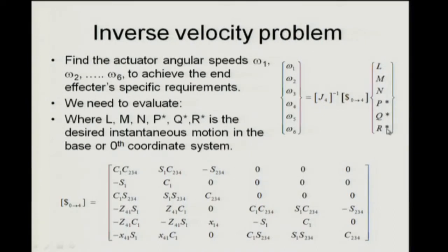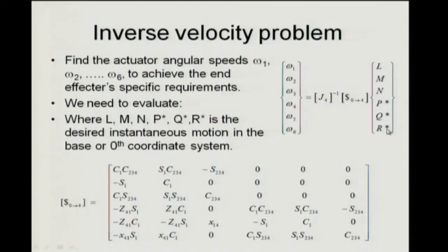So overall, this process is much more efficient than trying to find the Jacobian of the manipulator by some other means, and then you find the Jacobian, then you invert it. You could have gone by the DH thing using the method which I showed, not the definition method, but the second method, the numerical method that I had talked about. You could have done it that way, except that this is likely to be more compact and more computationally efficient. So is this clear?